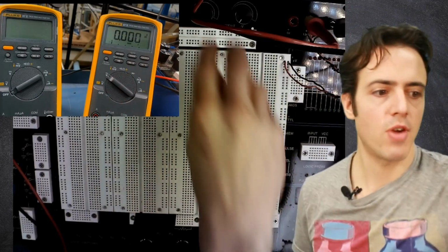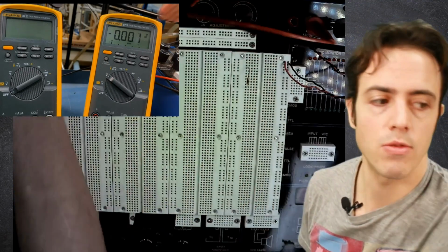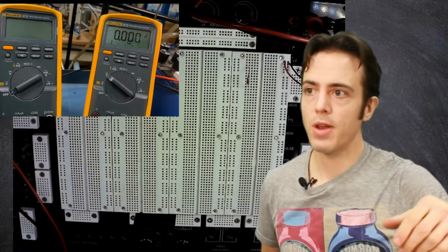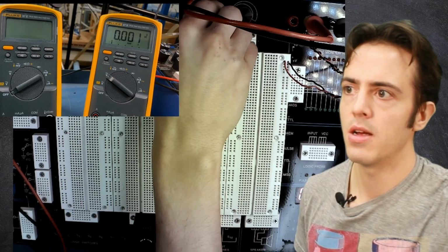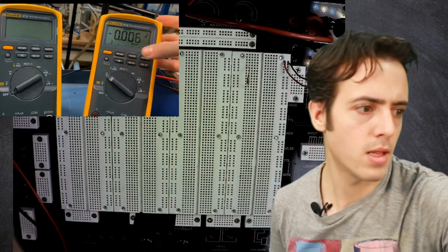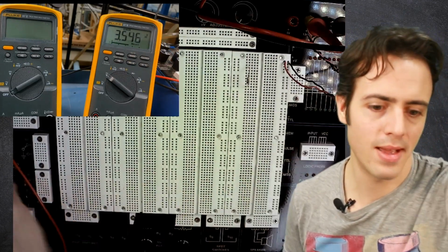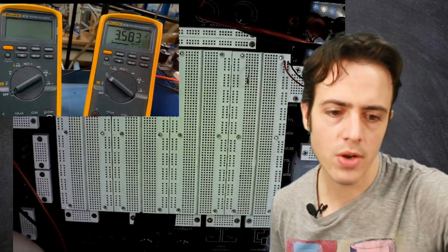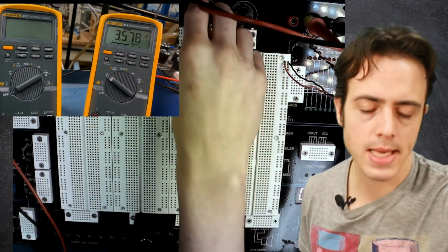If I try and turn these, nothing changes because there's a power button at the rear of the breadboard, which I can turn on. Thankfully, this one is plugged in. So if I now adjust these, this is probably not connected properly. There we go, it wasn't connected properly. So let's turn these all the way down to the bottom. The minimum voltage that I've got is 3.5 volts, which is a little bit larger than I was expecting, but that's fine.